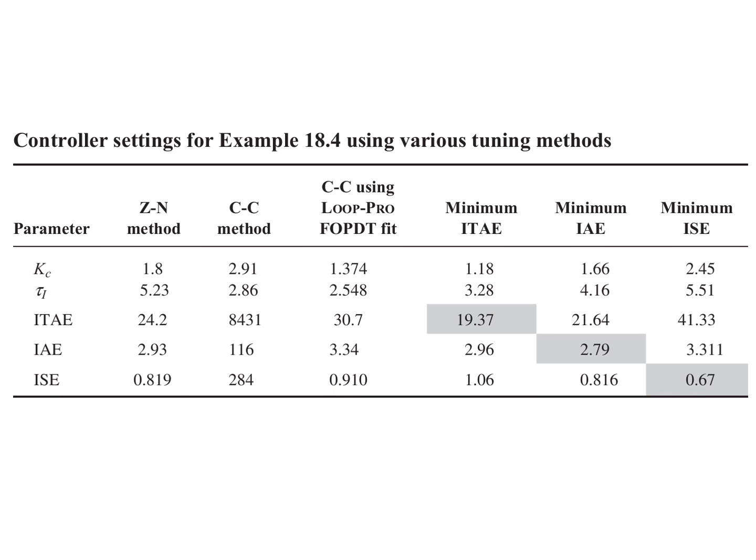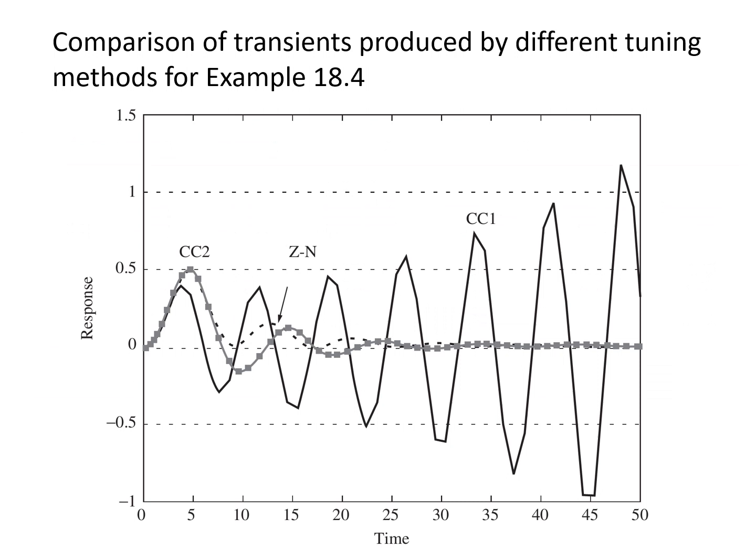And you can see from here, if you just compare Ziegler-Nichols and Cohen-Coon, the Cohen-Coon 1 method, where we saw the ITAE very high, looks like it's not going to be stable, increasing and increasing and increasing. The Cohen-Coon 2 method is slightly better, it's decreasing, going to the set point for disturbance rejection.